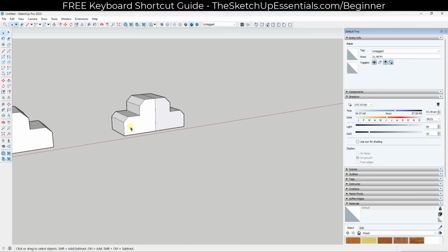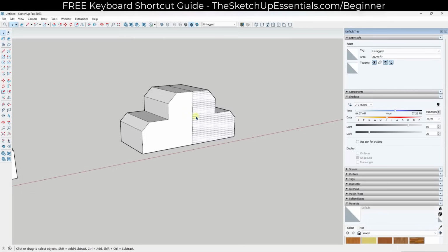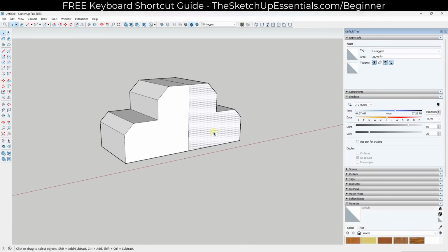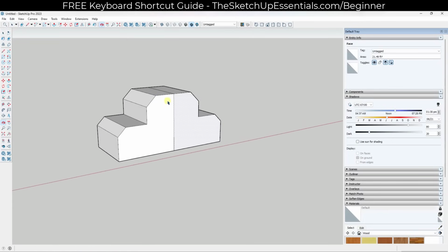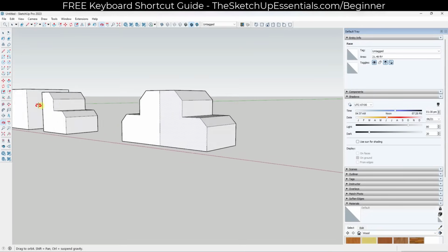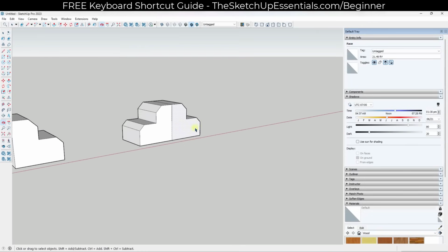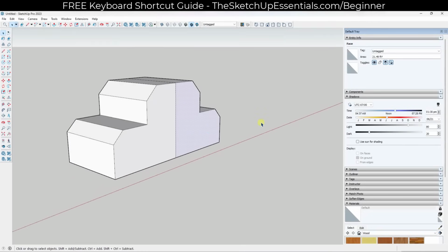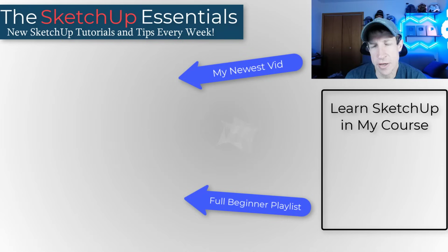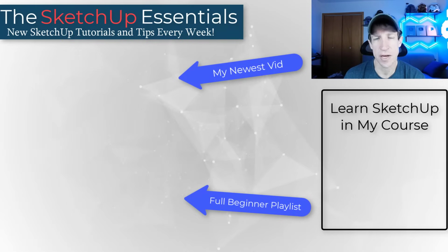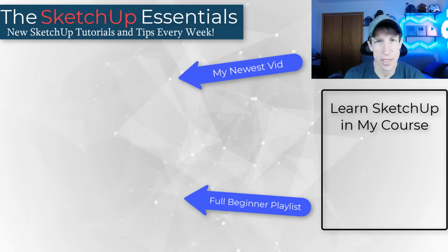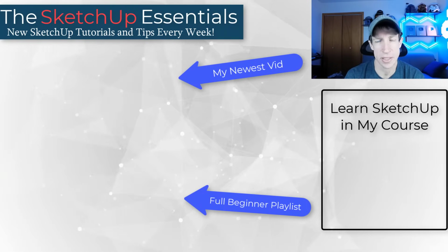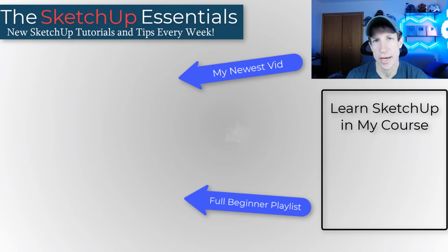So in general, when you start modeling elements in your models, I highly recommend that as you go, you group them to keep them from merging, because otherwise this can just get really nasty from a bunch of stuck together geometry standpoint. All right, so now you have a general idea of how to create three-dimensional shapes in SketchUp. In the next video, we're gonna go over some advanced tools for doing things like creating copies and other things like that that can make your life a lot easier.